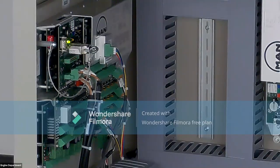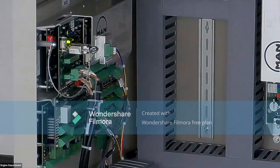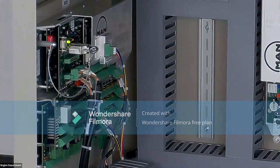So you are accessing the power supply from the engine control room. As I told you, inside the power supply cabinet, you'll find a 60 ampere breaker for each MPC. The power supply is 24 volts direct current. You are looking for the breaker tagged scavenge control unit, and you are switching off this breaker. Scavenge control unit, I switch off. You will notice that now the LED is turned off.